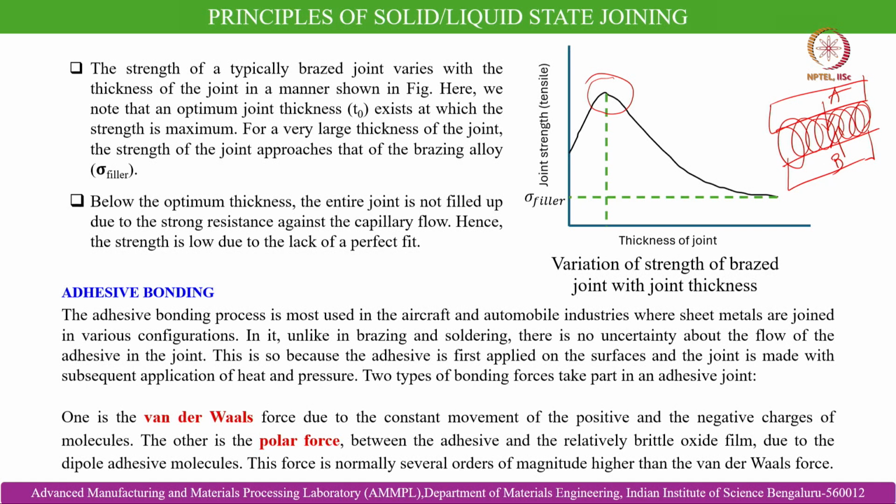That contribution to the joint strength will come from A and B until a certain thickness, say T. Then the joint strength gradually decreases, and after a certain higher thickness it is reduced to the strength of the filler material, which is always lesser than that of the parent bodies getting joined by the adhesive bonding technique.